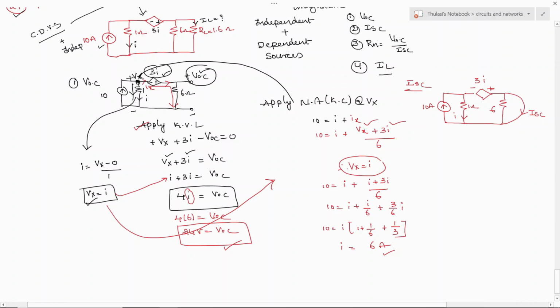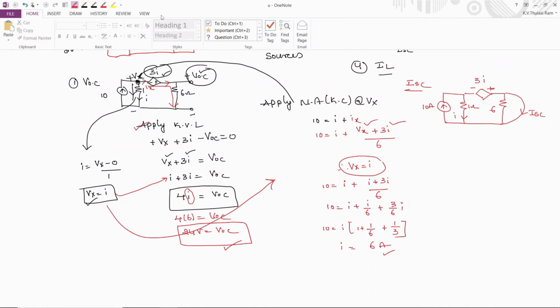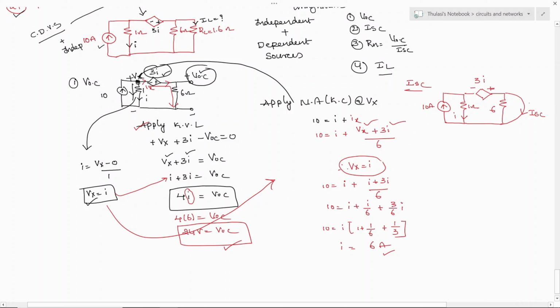So whenever a short circuit is parallel to a resistor, these two are connected in parallel. So for a short circuit parallel to a resistor, when you find the equivalent, this is of 0 resistance, this is of 6, 0 into 6 divided by 0 plus 6, so the resultant is also 0. So therefore you will be getting the same network.